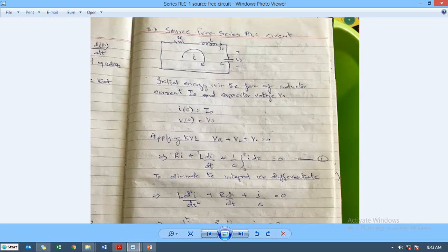explaining this circuit. So this is a series circuit excited by its own energy stored in the capacitor and the inductor. The initial current is I naught in the circuit, and the initial voltage is V naught across the capacitor. So the main variable which we are going to take here is the current I, which is the inductor current. Obviously this is the current for the capacitor and the resistor also, because this is a series circuit. But we will be capturing the behavior of this whole circuit by taking the main variable of this series current.